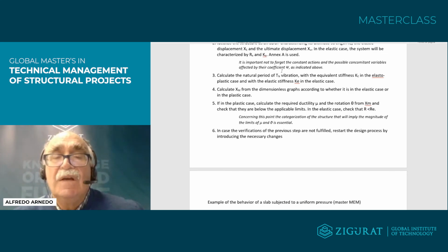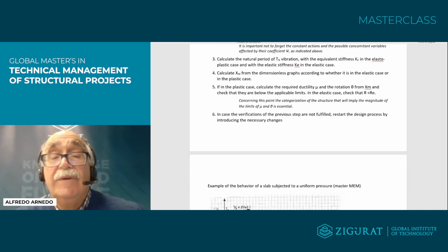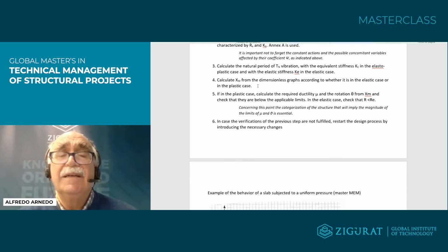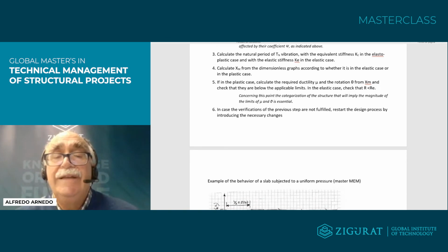So well, don't forget, I was forgetting the normal situation, the loads that are simultaneous and happen, and sometimes can reduce the margin of safety. So this is why, when we deal with a specific project, it is very useful to construct as light as possible. And consider that the explosion in that case is not coincidental with an earthquake or a maximum wind.